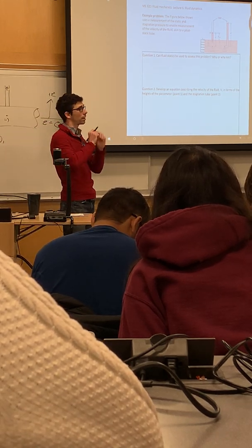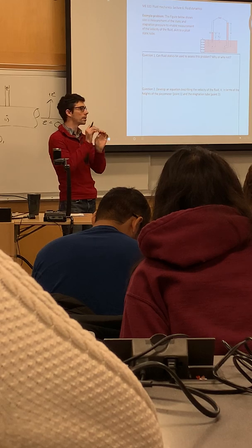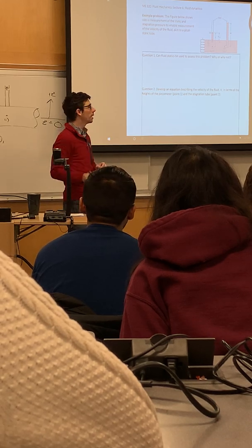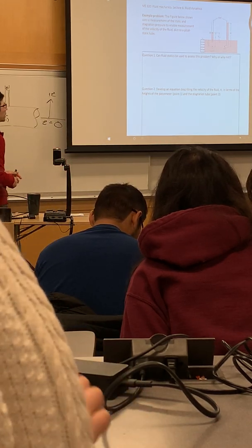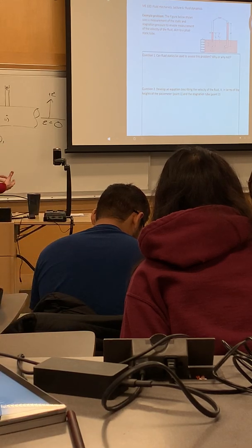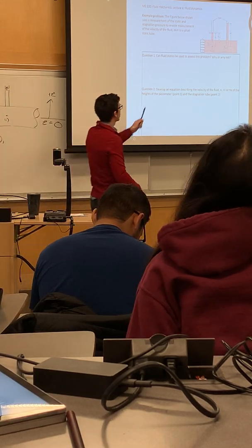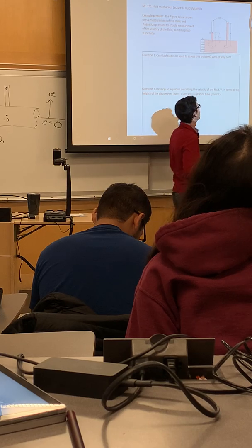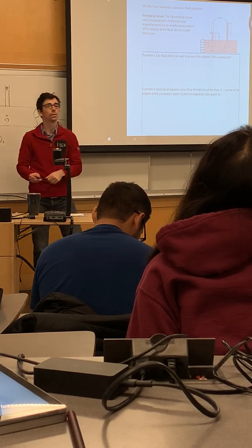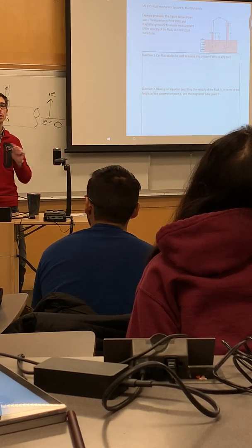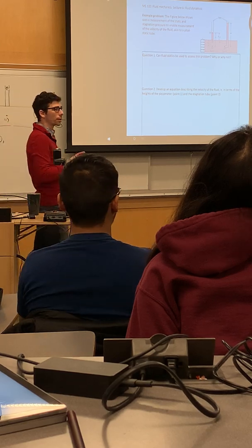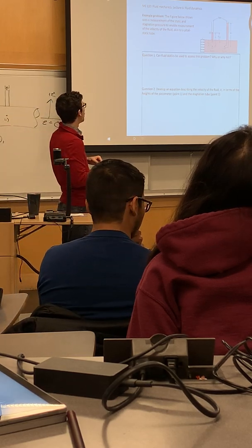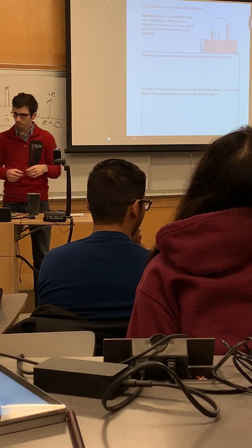In the book, you saw examples of pitot-static tubes that are all combined into one neat device. But this relies on the same principle, right? At one point in the fluid, we measure the static pressure. At another point in the fluid, we measure the stagnation pressure, right? And the difference between those things can allow us to extract useful information about the fluid flow.